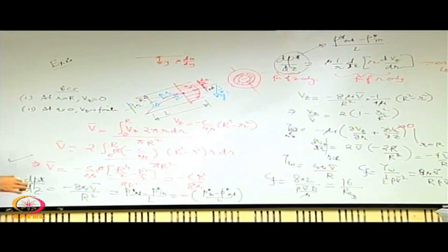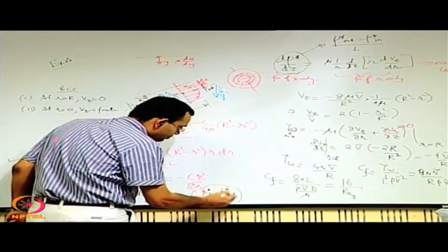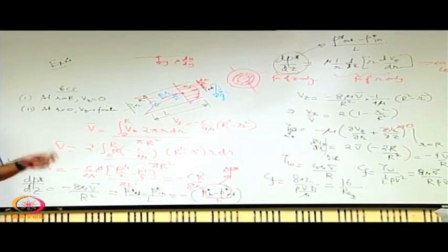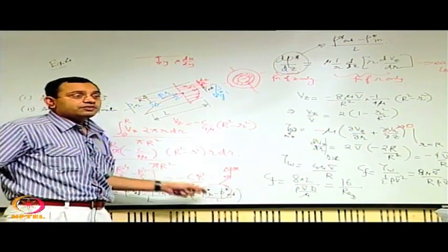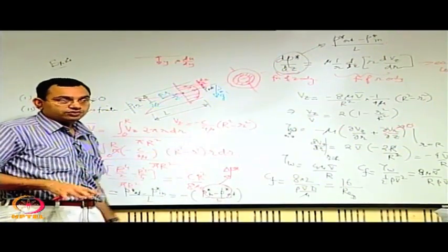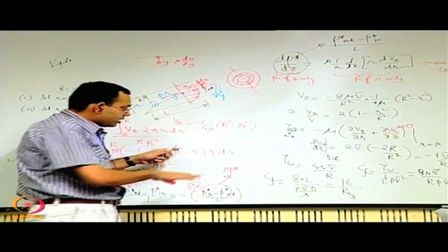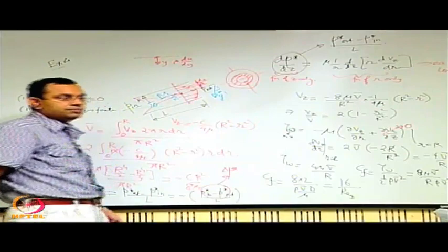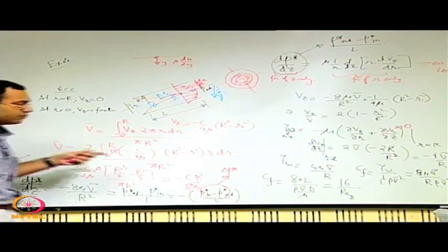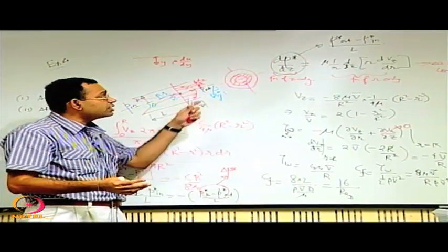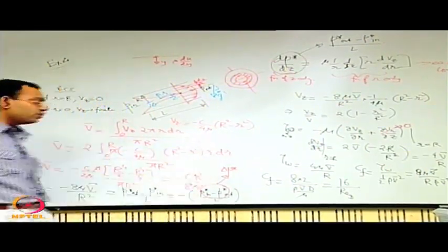Why we are writing it in this way is, the P star in minus P star out is the driving delta P star for the flow, the driving difference in piezometric pressure that should drive the flow. Why is this driving pressure difference necessary? It is necessary because you have viscous resistance in the flow. So you have to have a driving pressure gradient, a favorable pressure gradient, that is dP star dz negative, to make this flow occur.